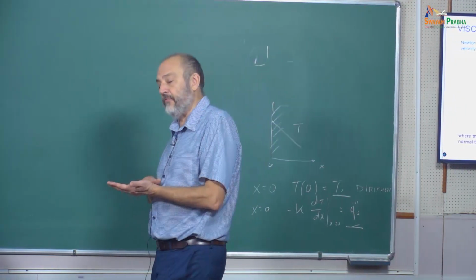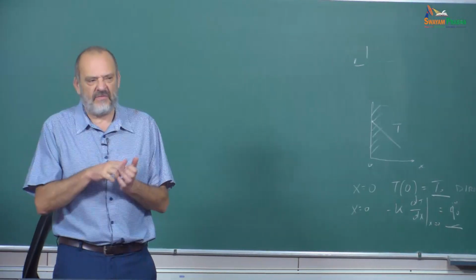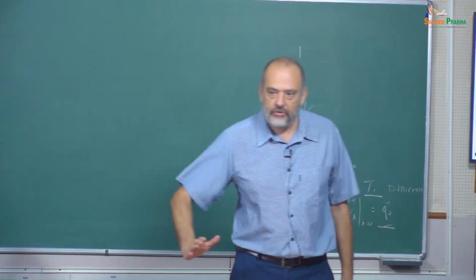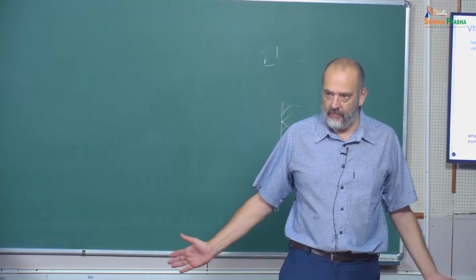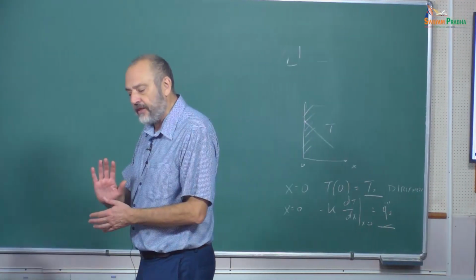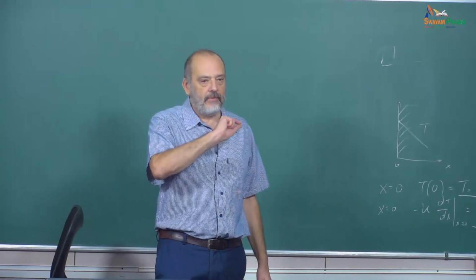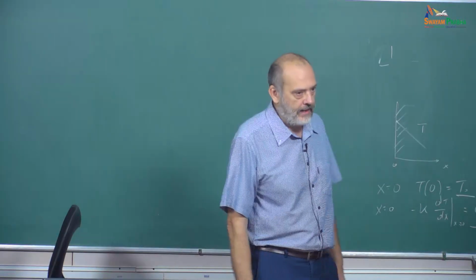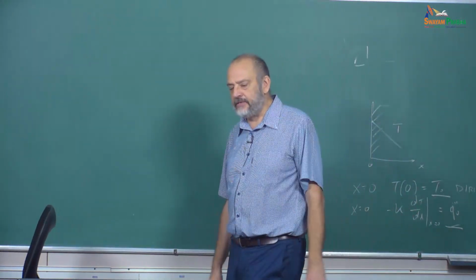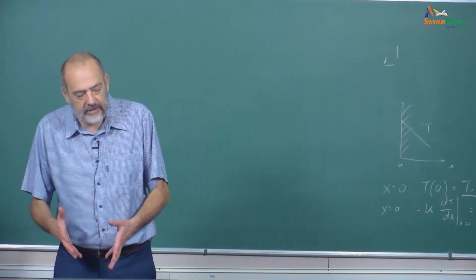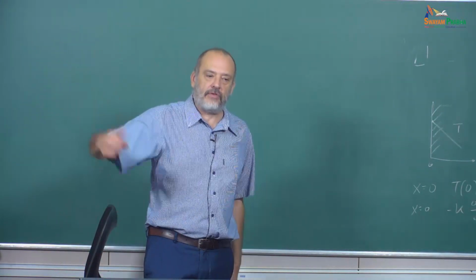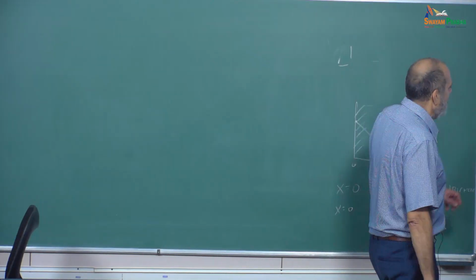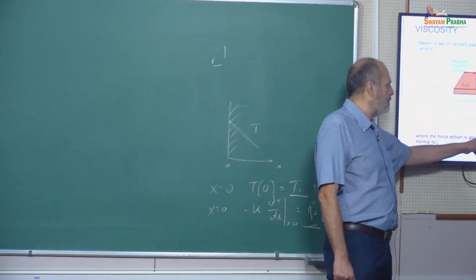Because if, for example, we are considering something very, very viscous, you can understand that if I want to push, I need to do some work. Otherwise nothing is moving, right? And this is really the force that we need to have for each of the layers of the fluid in order to put the fluid in motion. Something that we know, we have this law that is saying that this force is proportional to the gradient of the velocity.